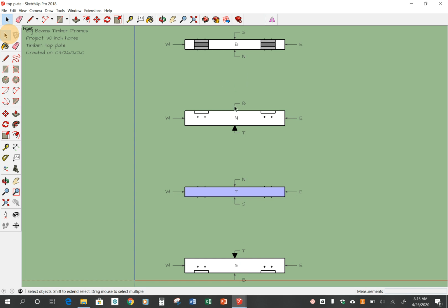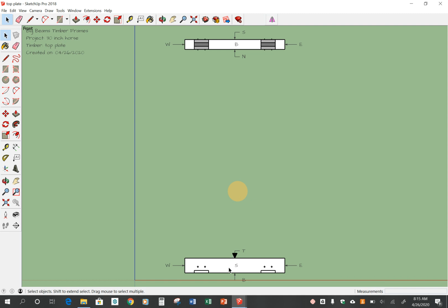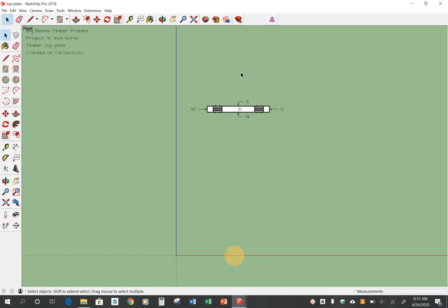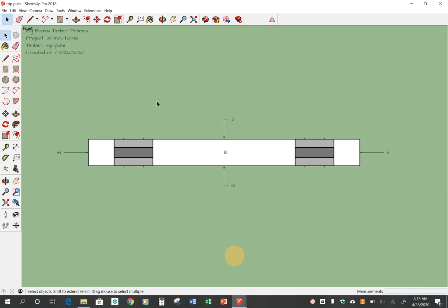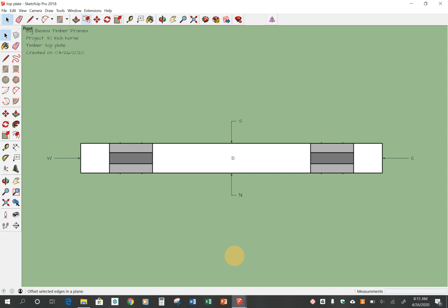So to do that, if I wanted to start with the bottom face, I would click on this one and hit delete. Click on that arrow and delete. Click on that, delete. Click on that, delete, that, delete. And then I'm using the wheel on my mouse to zoom in on that. So then I could come up here and edit that and call that bottom face.